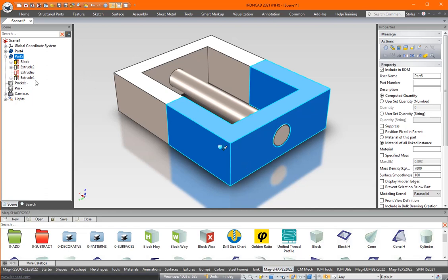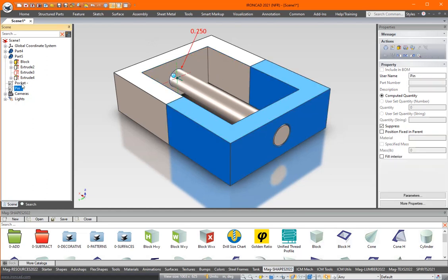In innovative mode, this gets reordered automatically because the CAD software is smart enough to know that if you're putting a hole on top of a hole, you've got a hole in material, you've got to reorder it so it makes sense. That's the innovative part mode, which is beautiful because it eliminates a lot of headaches. But in this situation, when you've got a lot of stuff driven off of other geometry, you may want to just lock the order of this.